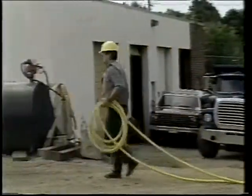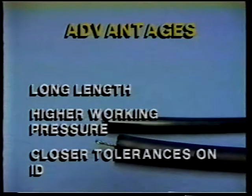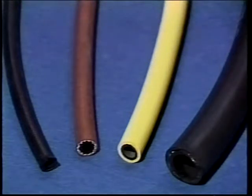Some hose constructed in this manner utilizes a flexible rod or mandrel to support the tube during manufacture. The long flexible mandrel is made of plastic or rubber and permits the application of stronger reinforcement over the outside of the tube. This construction gives the advantage of long length, but with higher working pressure rating and closer tolerances on the ID. The inside diameter is generally limited to 1-inch ID maximum.